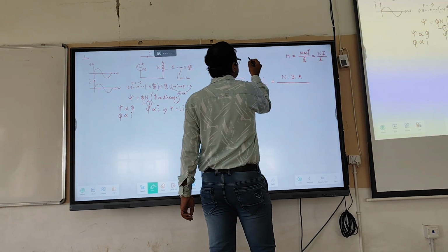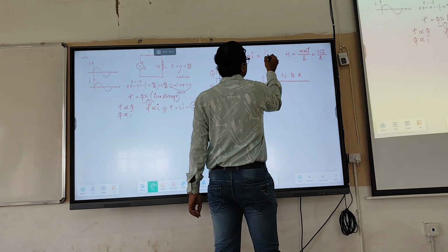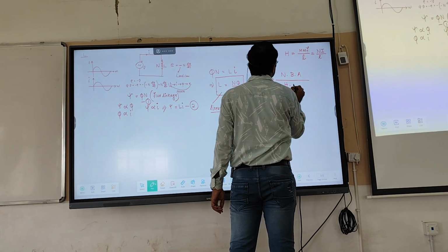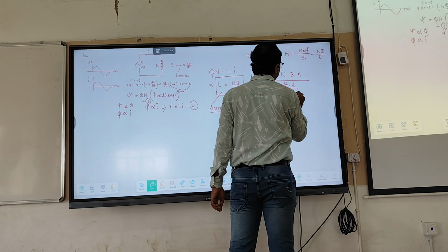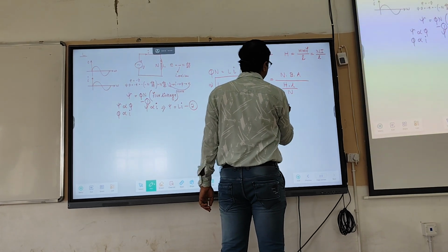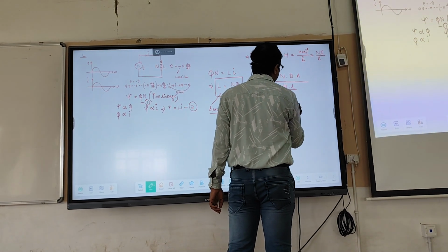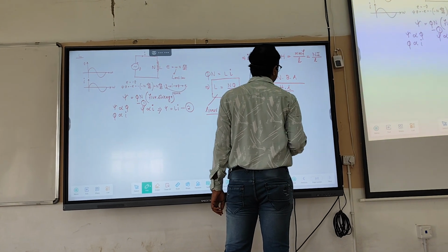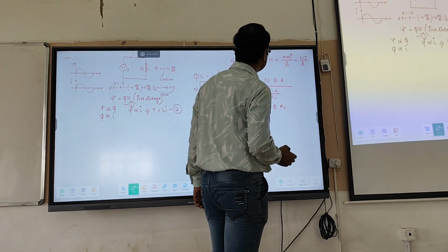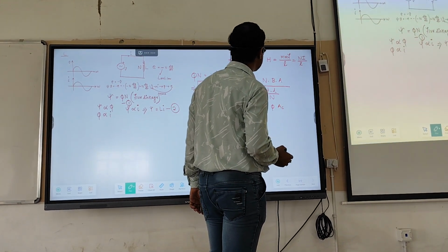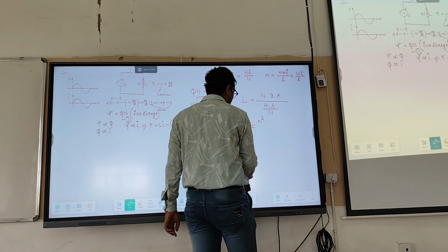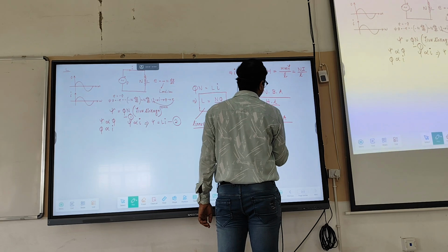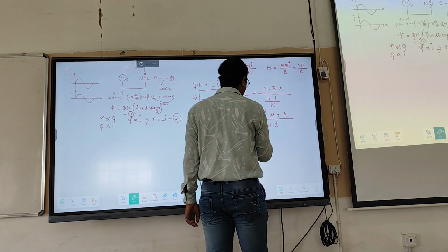So I is equal to H l divided by N. If I put that here, then the formula is N square. How can B be written? B is phi divided by A. B is equal to mu into H, so L is equal to N square mu into H into A divided by H into l. This is the formula actually.